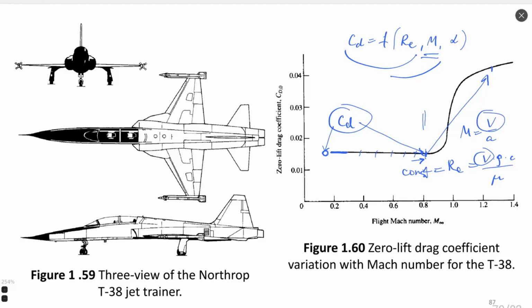It gives a difference. It's not so simple, right? Just use another velocity and simulate, or just use another velocity and calculate. No. You need to keep Reynolds number. It means when changing velocity, at the same time you change the size of the body, or you change the viscosity, or you change the density of the fluid to keep Reynolds constant, because drag is significantly changing with Reynolds number, as we saw before.